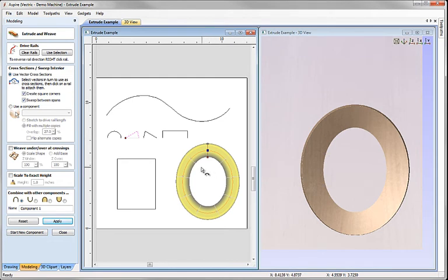Now there are various other things I can do with the right mouse click menu. If I right mouse click over part of the curve here, then it gives me the option to insert a start point. We've seen how we can remove all cross sections, and also if I'm over a node on here, you can see that the cursor changes and displays a little crosshair there as I move around and go over the nodes on my drive rail. And if I'm over that point, then it would give me the option to make that the start point of my curve. If we click on that, it's going to change the location of the start point. In this case, that won't change the shape we're making, but it might do if we had other cross sections hung on this.